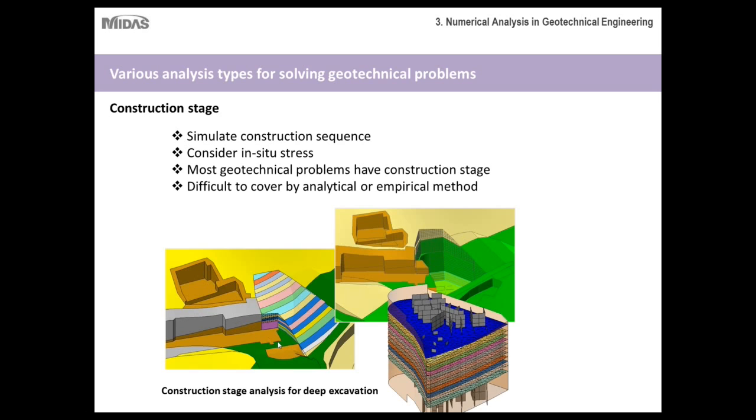As you can see, even the excavation itself, the layers were separated, and then later on during the construction of the basement foundation, the piles were separated. The basement layers were separated into different stages. So later on, when the analysis is complete, you can combine all of these stages to get a really detailed understanding of the effects of the excavation and the construction on your foundation and the adjacent structures.